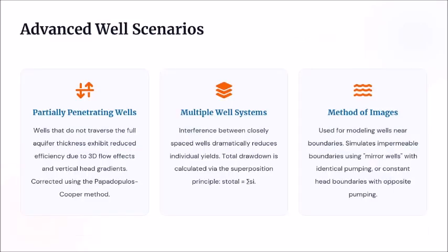Next slide. Advanced well scenarios. In the real world, hydrogeologists face advanced scenarios. First, partially penetrating wells. If a well doesn't reach the bottom of the aquifer, it causes 3D vertical head gradients and reduced efficiency, which must be corrected using the Papadopoulos-Cooper method.